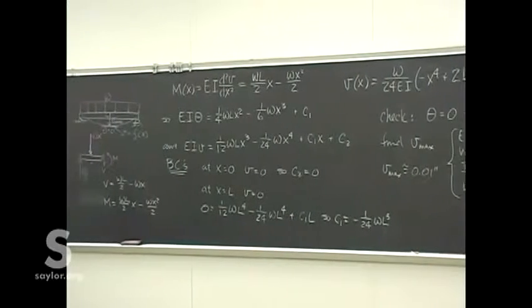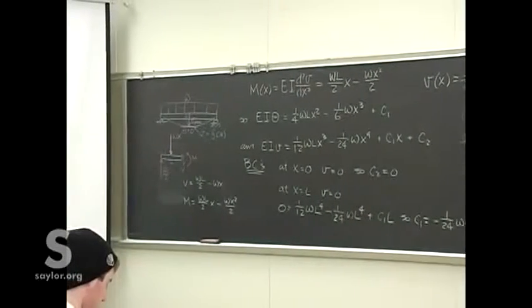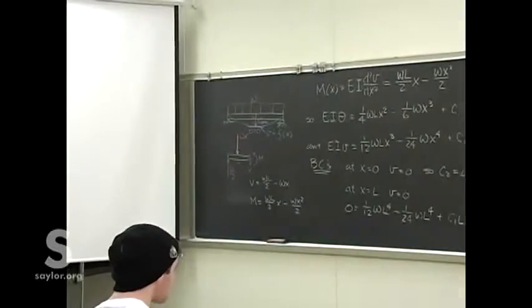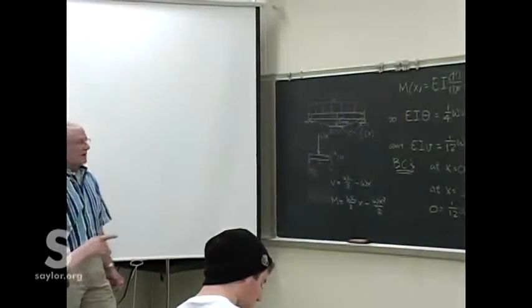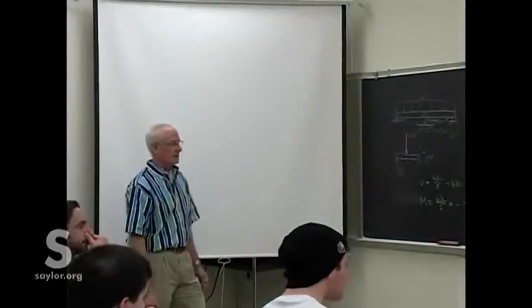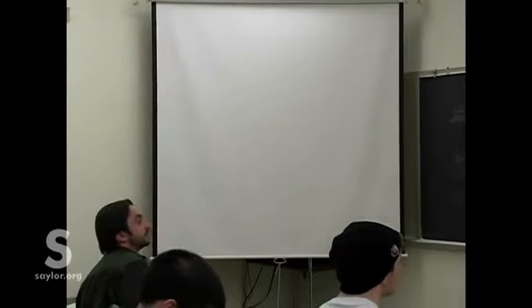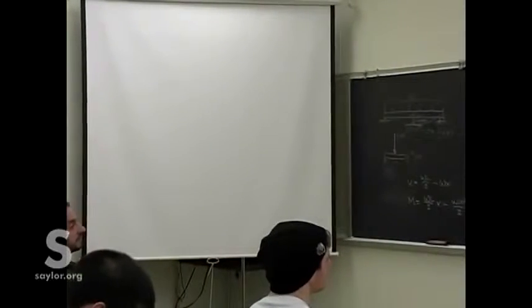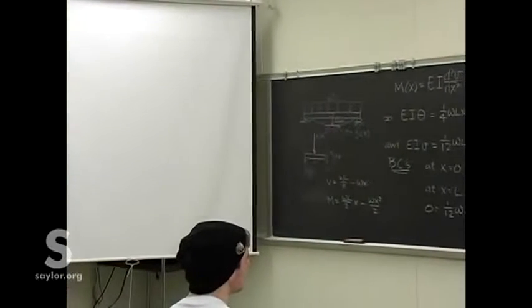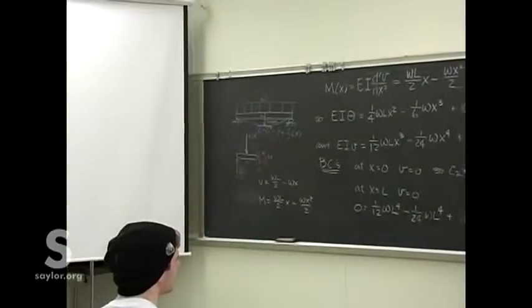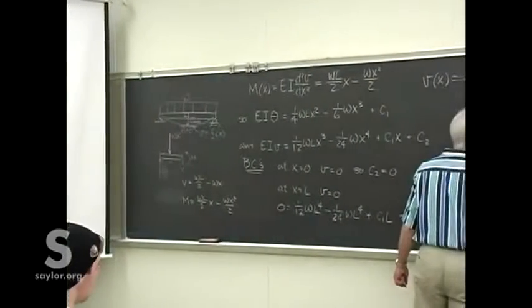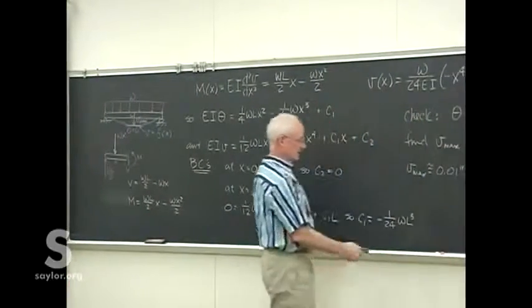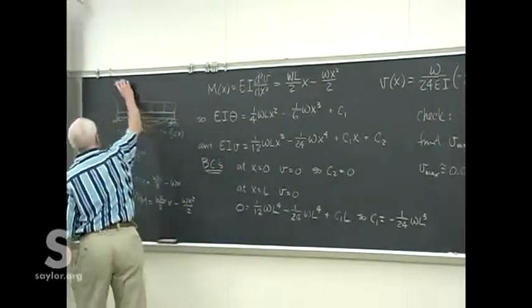Very, very small, which is good. You put the beam up there, you don't want a big gap that you now have to compensate for as you build other things on top of it, especially if you do something 6 inches to the floor. Well, you had to make all the units work. This was 10 to the 3rd KSI. You probably want that in PSI, so it'll be 10 to the 6th PSI. Pounds per foot. The length in feet, you want all this stuff in inches.